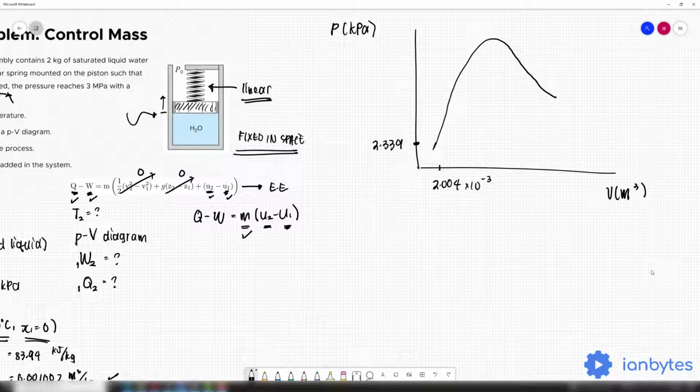So it means na yung ating point ay somewhere here on the left part of your saturated curve. So let's say that our volume V2 is somewhere here. It's equal to 0.1 cubic meters. And you know that it is located somewhere inside this saturated region because it has a quality that is between 0 and 1. Let's say our pressure is somewhere here, 3000 kilopascals. And our state point is located somewhere here. If this is 0.1, then we have 0.2 over here.